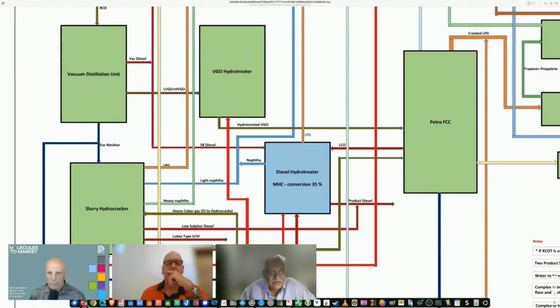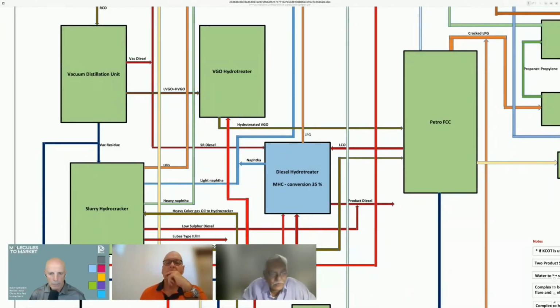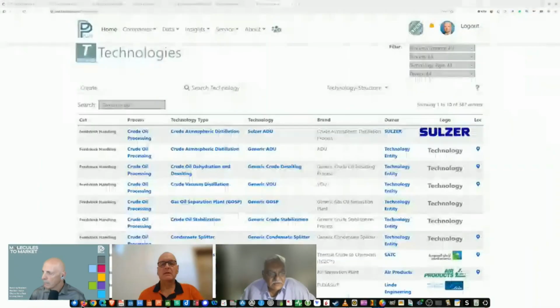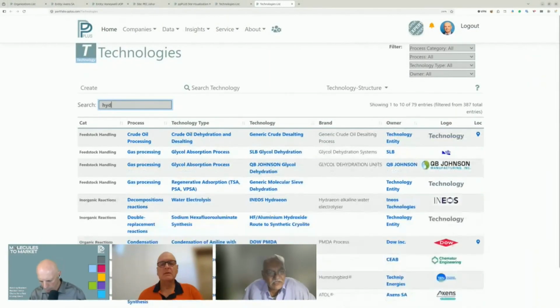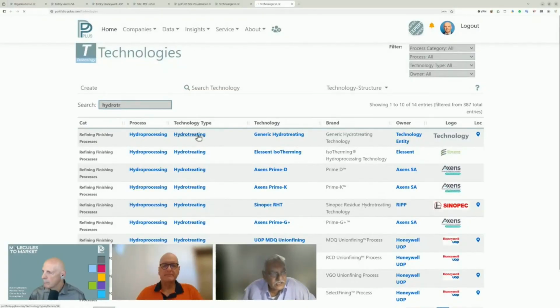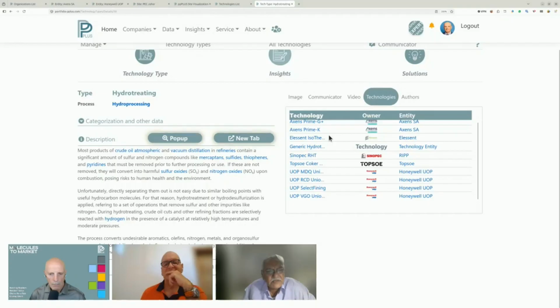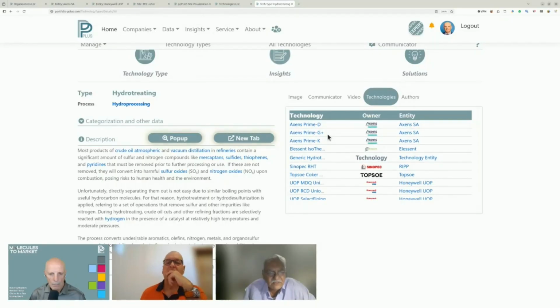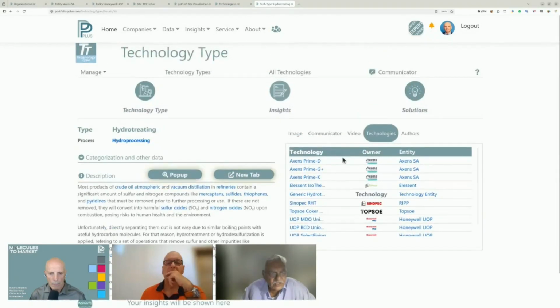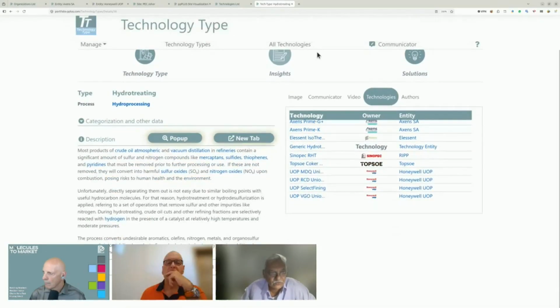Come to DHDT. Again, no problems. UOP, Axens, both of them have this technology. Topsoe also provides this technology. So if I have to do common licensor selection, Topsoe is the third agency which can provide that. There are others also, but the game is if I have to go for a managing licensor and make a choice between Axens and UOP, I don't have a problem because both have this technology. ABB and many other people also have the technology. But if I'm looking at UOP and Axens who have a complete basket of processes, VGO hydrotreater, DHDT, again, no issue. Let's come back.